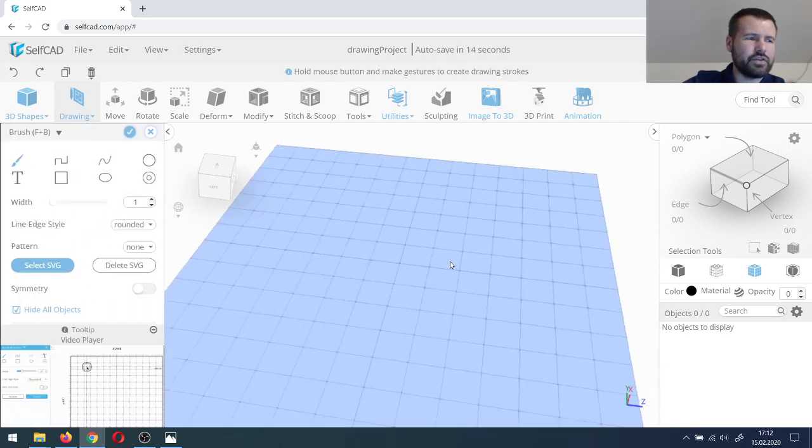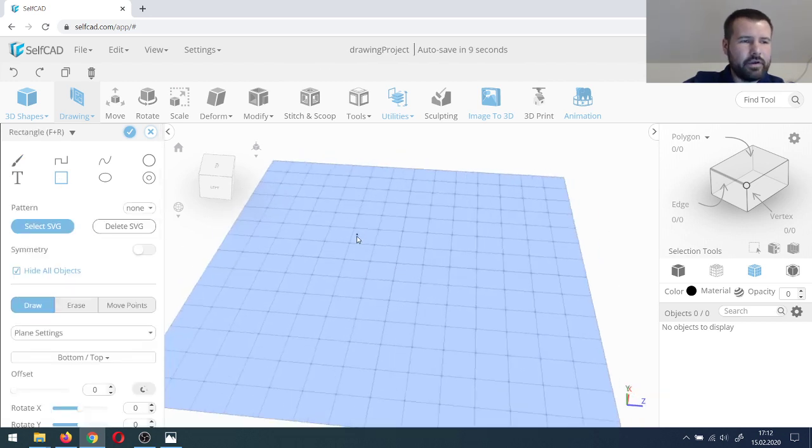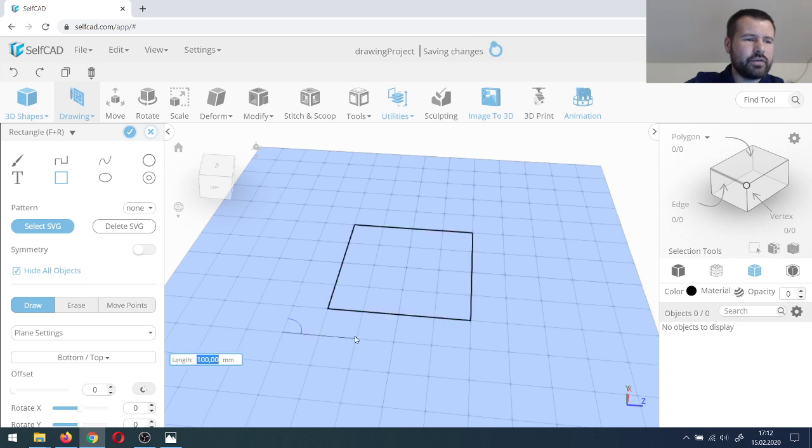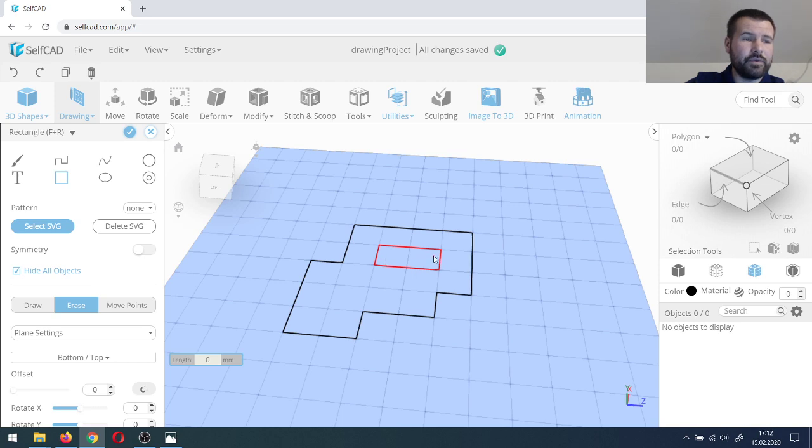Freehand, this is something I already explained on the last webinar, has a functionality that we call clipping. Clipping means that whenever you draw something and you start adding different parts to it, the solutions actually get connected. So if you, for example, use draw, it will add to the existing shapes whatever you choose to draw next to it. If you use erase, it will actually act as an eraser, but you can also use erase in the middle of the shapes to actually create something we call holes.